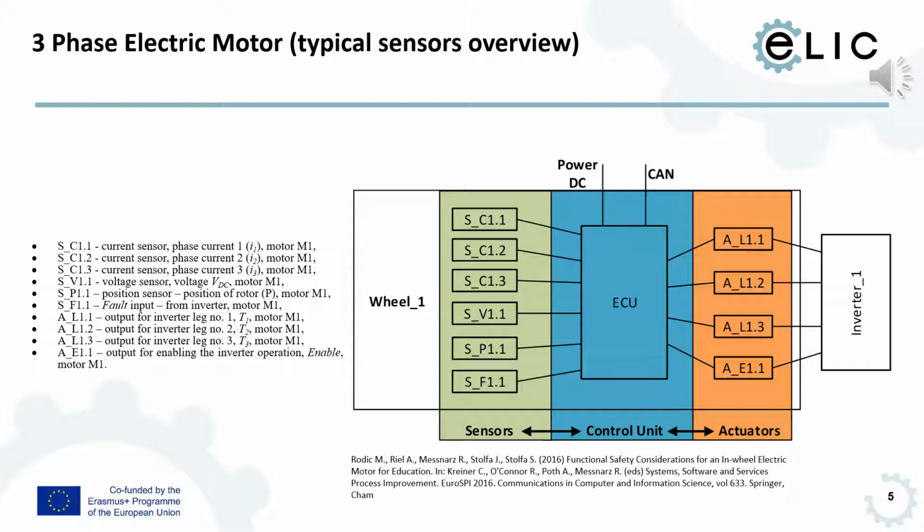So we would have sensors measuring back the current sensor 1, the current sensor 2, and the current sensor 3. And then there are some mathematical and physical laws with which we can check that the currents are correct. Which means that when we control a motor, there is a Kirchhoff law, for instance, that the sum of the 3 phase currents should be around 0.